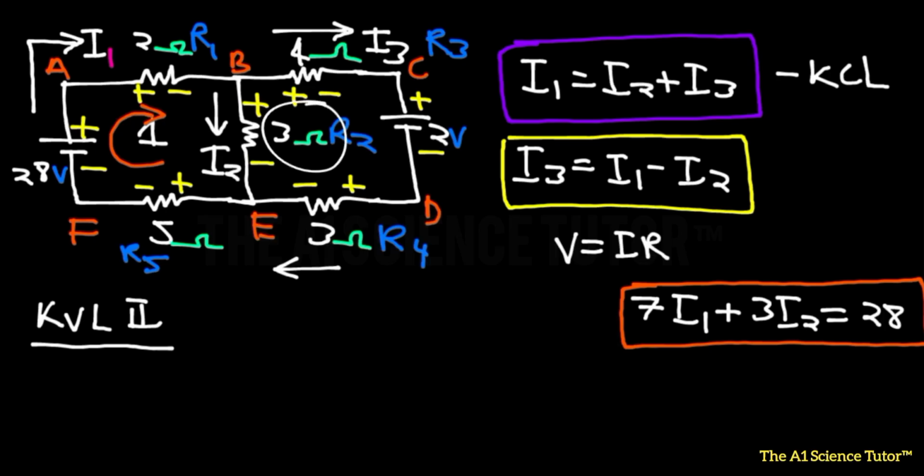So let's start with this one. The direction for the analysis will be this way. That's because we have already started with this, and this battery is really just a small battery, it doesn't have so much EMF, so that would not cause the current to go this way. Now we're going to start with the first element, which is the 3 ohms, and that ends on a positive note, so that will be plus.